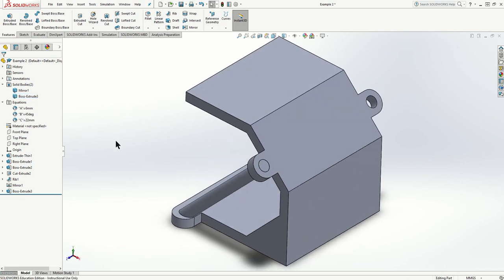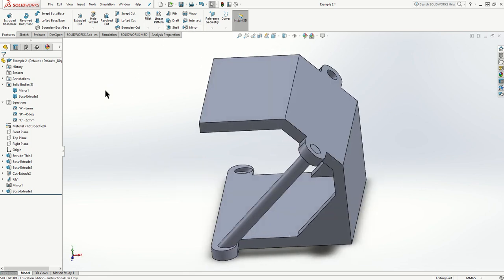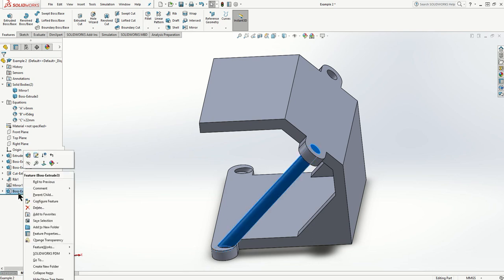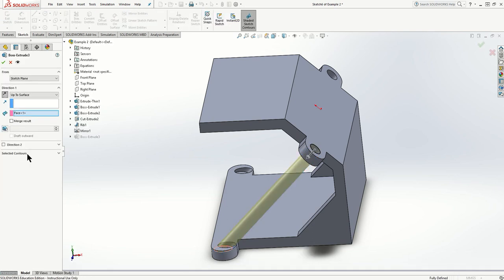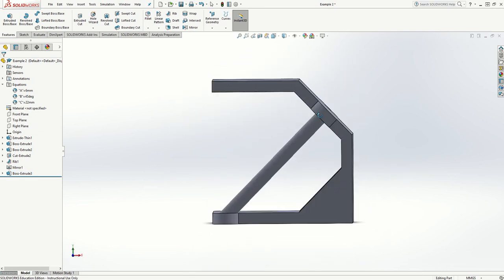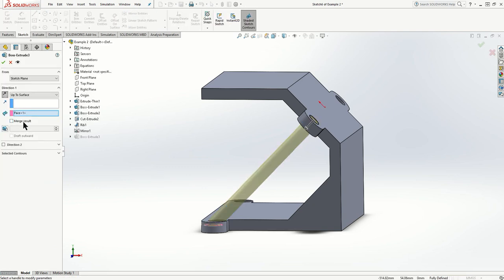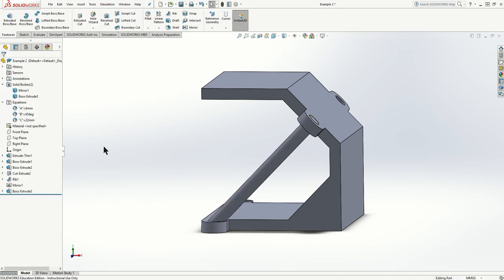Now that that piece is done, I could do the same thing I did prior and do the mirror option. Just to show you what happens if I didn't do the extrude join, I do feature. So now look what happens if I leave merge results, right? And I press OK. What's going to happen? A, the hole's gone. B, it's all one piece. And if I go look here, it doesn't tell me anymore that I have different bodies. So I would go back here, edit feature, and make sure to uncheck merge results. Accept it. And then again, now I have back my solid bodies.